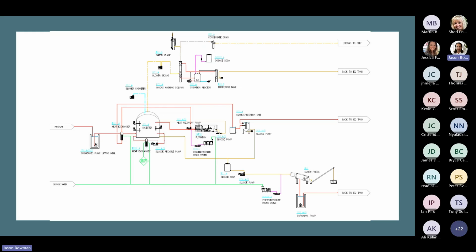Typically, we would have a struvite removal or dephosphorus unit, let's say, external to the digester recycle. In those cases, what we're trying to do is reduce phosphorus. For those of you that know a little bit about struvite, it's a magic combination of magnesium, ammonium, and phosphorus. It's a 1-to-1-to-1 molar ratio. Sometimes these systems may have an abundance of ammonia and phosphorus, but they don't have magnesium.